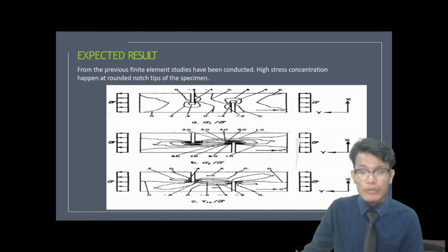The shear stress for the 0° specimen at the notch tip has a stress concentration factor of 1.57. At the center of the specimen area, a thin region of uniform shear stress is equal to 0.6, indicating we can measure the shear strength by using this method.